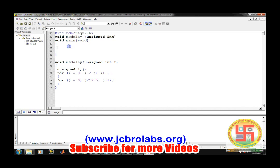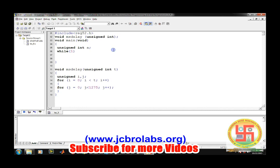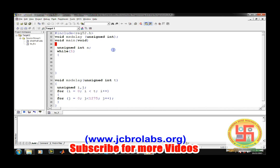First of all, as we have discussed, we need to create an unsigned int a. This variable a will read the content of port 1, because the sensor output is connected to port 1. Now we create an infinite loop, because we want it to work continuously. Now let's first read the status of the pin. We read the status of the port with masking, so that only pin 1.0 is accessed. So P1 gets ANDed with 0x01.